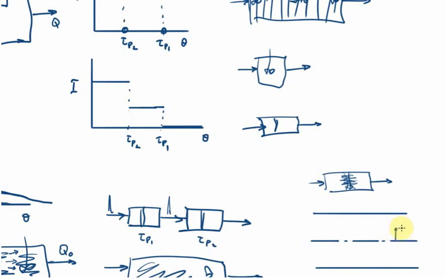So let's say that's r, and then we can question for ourselves at this radial position, and of course that goes around like so. So we've got flow through this set of radial positions, right? So between r and r plus delta r, there are these flows, and so there's a certain flow rate that will come through r and r plus dr, and we can estimate this flow rate.